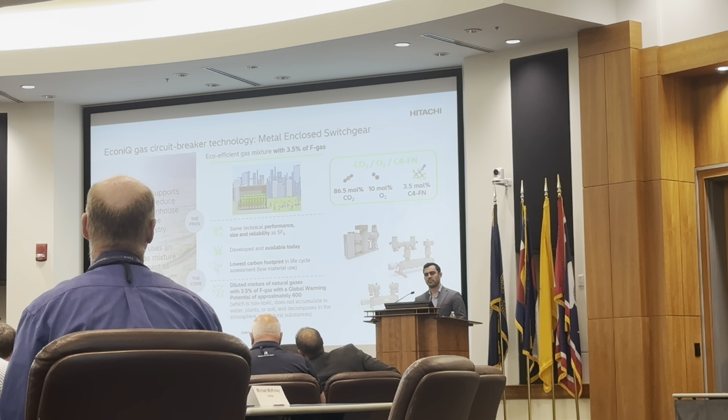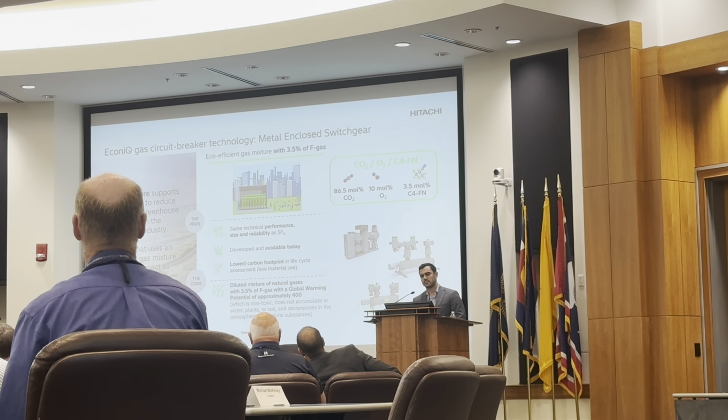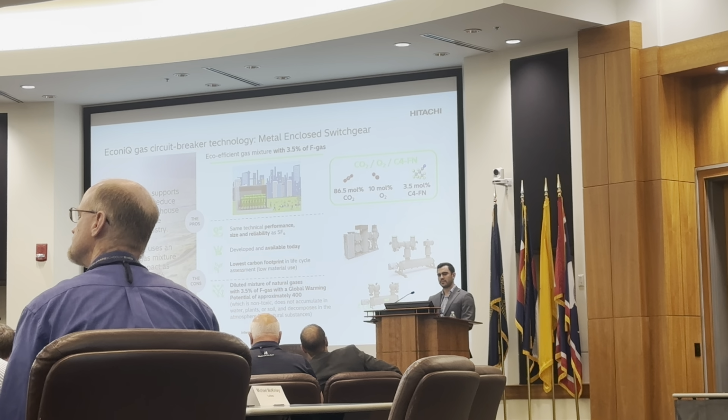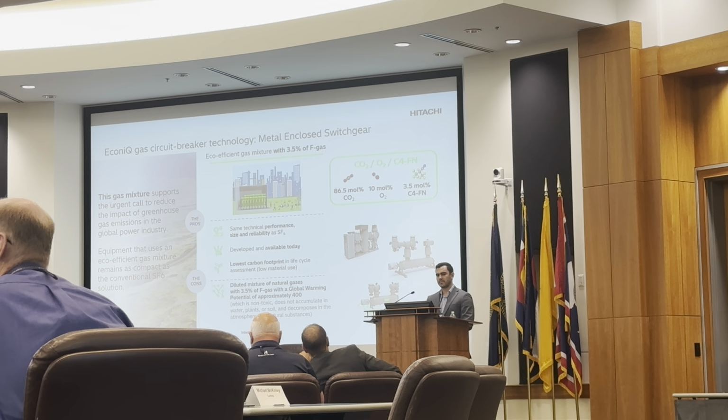So on the SF6 side of things, we usually look at purity and moisture. Are you still looking at the purity of those molecules, making sure that's still holding up with the continuous duties of insulating and deactivating? Yes, we have done tests on the life of the gas through normal arcs, regularly arcs and heavy arcs.